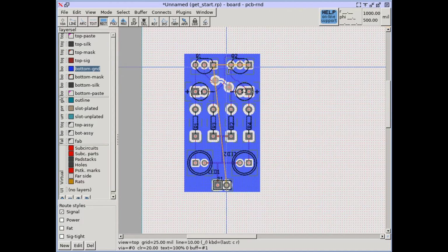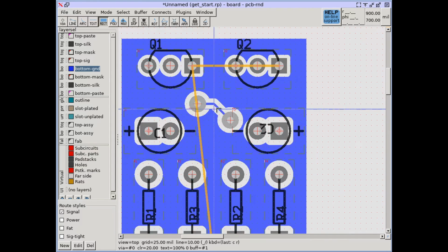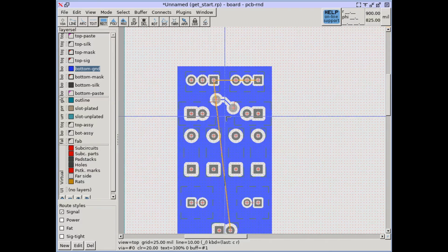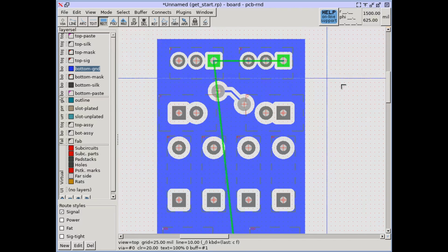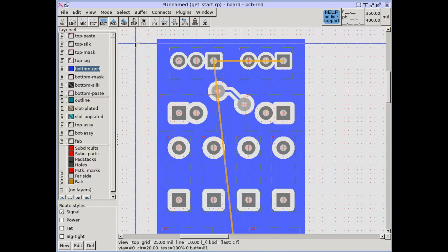Copper objects, other than terminals, are not associated to nets, so the new polygon is not a ground polygon, just a polygon. It has clearance to other copper objects by default, which means our 3 ground pins are still not connected. The easiest way to connect them is adding thermals on those 3 pins.